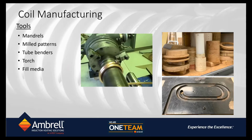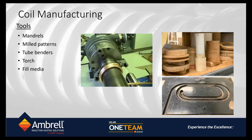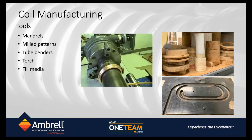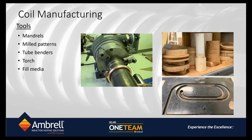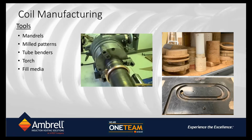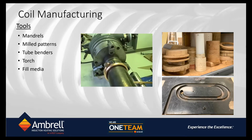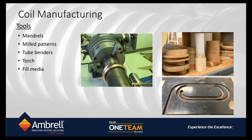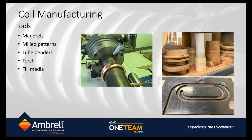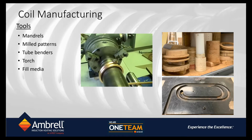So this customer, for example, had ordered 50 induction coils from us that were all round. So it's not a very difficult shape. But when an operator has to wind the copper tube by hand around a wooden mandrel, it's hard to put the same type of force and pressure on the copper tube. And then when the copper tube is wound, there are differences in spring back that are achieved. So that's where a machine like this is very helpful to wind the copper tube and give repeatability in the coil manufacturing.